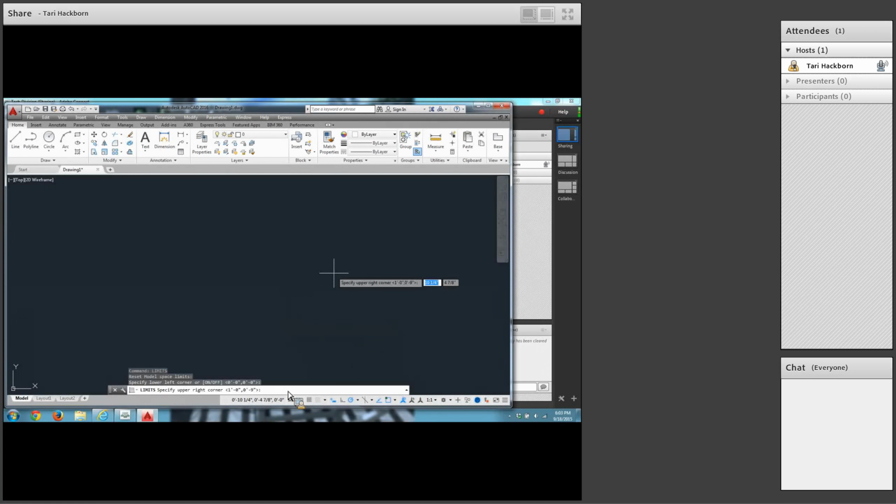The upper right corner is what's going to set the size of your drawing area. This is where you will type 60 feet, comma, 40 feet. Single quote for the feet. You need the foot sign or AutoCAD will assume you mean 60 inches. Okay.